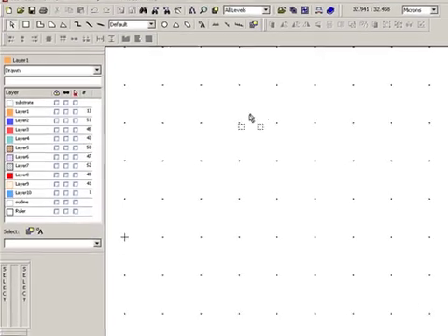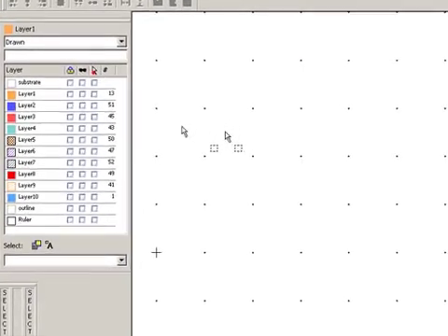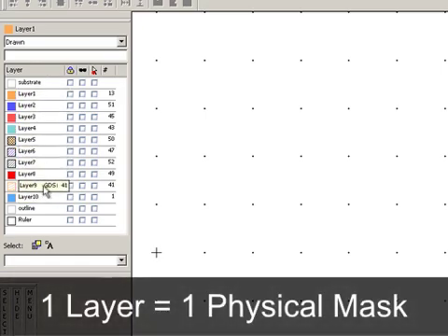Alright, so when we first launch LEdit, you are going to see a layer palette on your left-hand side that should look something like this. If you're working in NanoFab, you're going to find 10 drawing layers, basically just named layers 1 through 10. We've created a design environment file that provides you 10 drawing layers that you can use for creating your features.